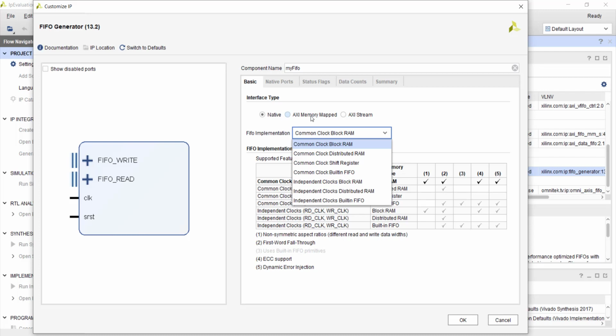For the Zynq FPGA, which comes under the 7 series FPGAs from Xilinx, the size of this small memory is only 36 kilobit. Okay, one small memory is only 36 kilobit, and depending upon the FPGA, the number of these small memories varies, like the lookup tables and flip-flops.